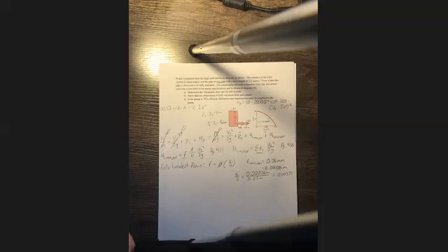And it looks like it's about a quarter of the way up between 0.02 and 0.04, which would put the friction factor, for 0.00371, at 0.025.